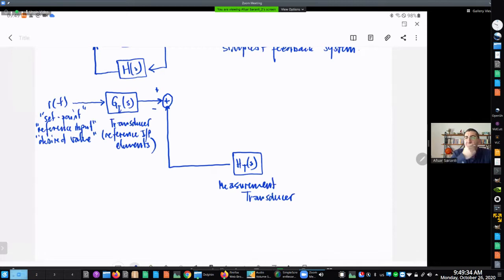If you have ever worked with these radio control servo motors, small black boxes, these are actually control devices. Inside there is a gearhead motor, so motor and gear, but there is also a measurement transducer, a potentiometer, which effectively measures the angular position. And there is also inside an electrical circuit which is basically an analog feedback controller. Okay, so what happens is that this servo device is able to control the angle based on the reference signal that you supply to it.